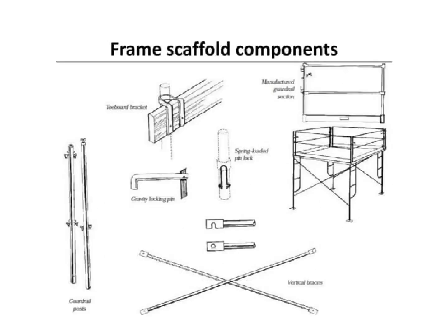Identifying the roles of frame scaffold components is essential in scaffold construction. To ensure proper safety and usage, the components should be chosen carefully to make sure they are fit for the job requirement, can support the weight of the load, and are compatible with the other components used. When the components have been installed, inspection is required to ensure they are in good condition and ready for use. Make sure to follow the manufacturer's instructions on assembly and check for secure connections.